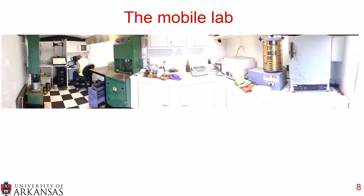Now, this was the mobile lab that we used, and this mobile lab allowed us to look at the plant mix lab compacted. So we set this trailer up. This is a 360-degree view of the trailer. When you walk in the door, immediately to your left is a Marshall compactor. There was a bulk water bath, a little bit of storage, a load frame, area for computers.